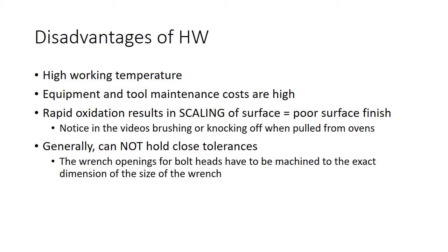And because it's hot, your equipment has to be specialized, and the tool maintenance is more difficult, because you're taking hot metal and putting it on an anvil and hitting it with a hammer. You're going to slowly heat up the anvil, and you're slowly going to heat up the hammer, and it becomes a bigger problem in rolling.